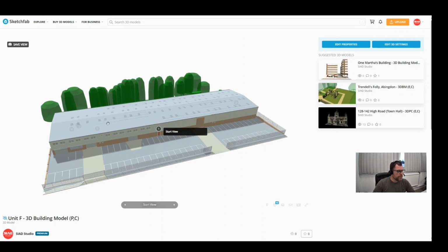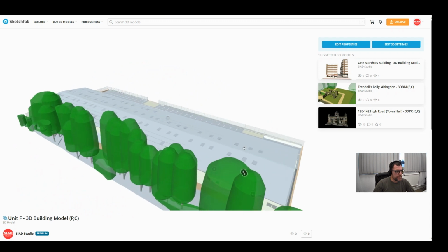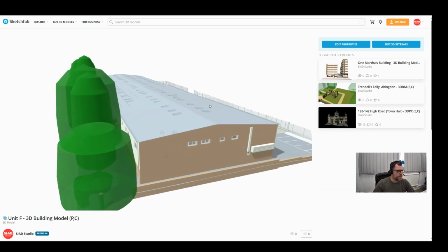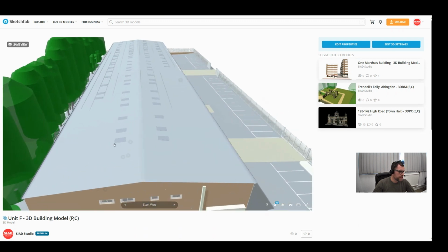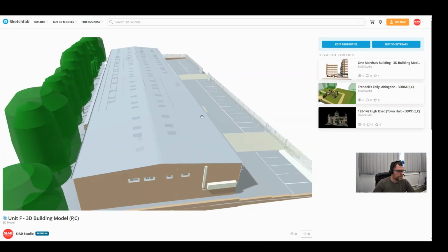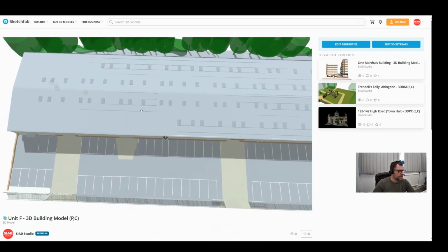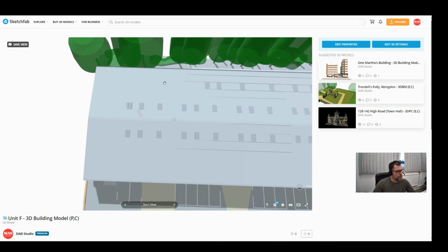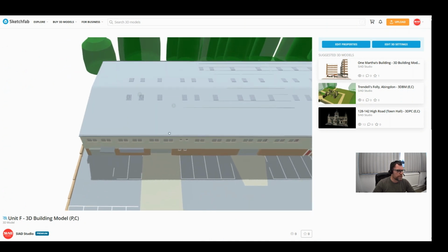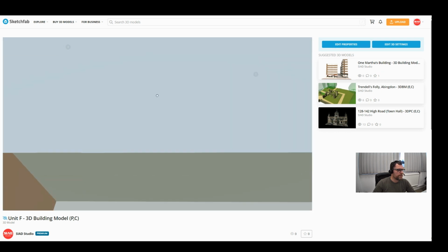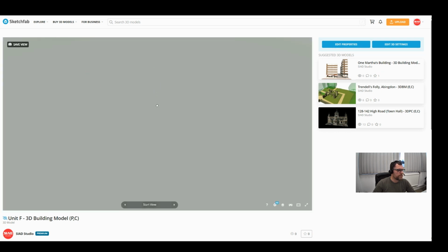Just one final thought. The only thing I've really picked up during this whole exercise is there is limited skylights, which probably aren't as apparent at the minute because of all the partitions and ceilings in the way, but over the actual office area you want to keep. So I think maybe we should look to populate that with further skylights before, or as part of the roofing project. So you've got a decent amount of light on the top floor, and then whatever we choose to do later on, that can be mirrored through into the openings in the first floor.